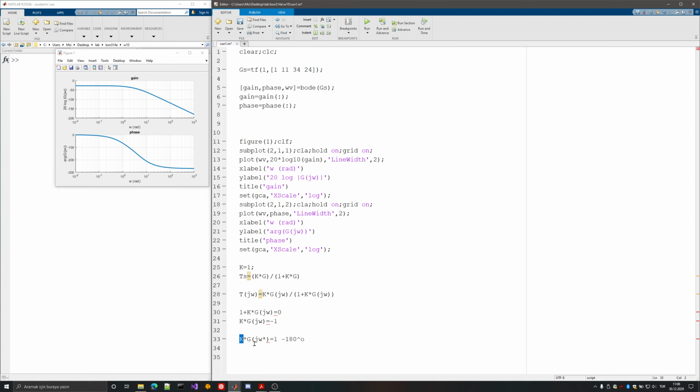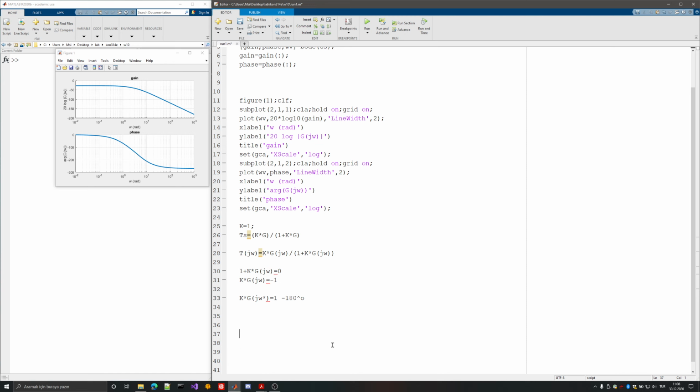But since k, in the sense of root locus for the p-type controller, I'm maximizing k in the 0 to infinity interval. And then I reconsider the whole system in 0 and minus infinity. So we don't use them simultaneously. So if k is a positive controller, which is preferred, by the way, no one wants a negative valued controller, even if it's a static controller. But, well, I know basically that k will be contributing to the angle with 0 degrees, which basically means that it will not contribute to the angle.